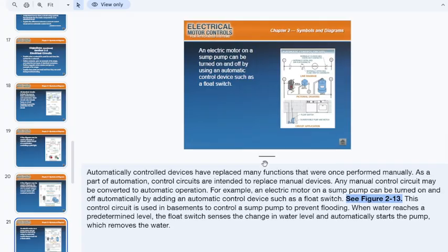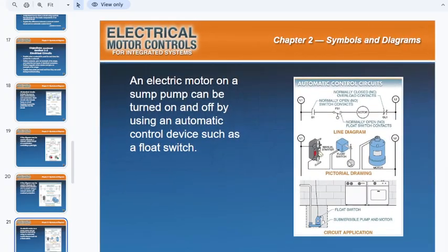And this one in particular is the pump that I was talking about, the float switch or level switch sometimes. This is what is inside your gas tank, a float switch. It's called a fuel pump, but the fuel pump has a float switch on it. So sometimes wells, this is what they're showing us here, a submersible pump down in some sort of pump location, and it has a float switch, and as soon as water fills up into that area, that float switch will mechanically kick on that motor.